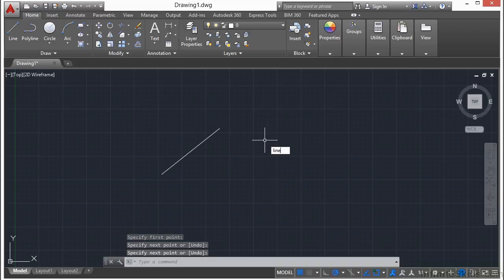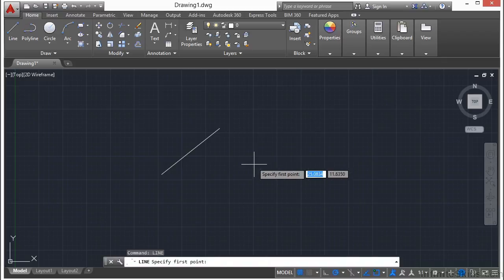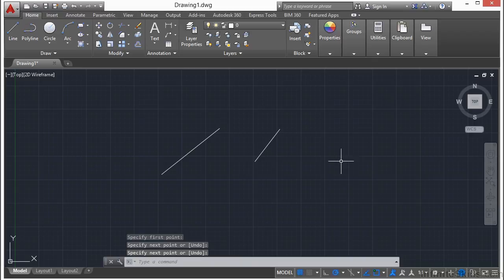Also, I can just start typing. I don't necessarily have to put it down in here. What's going to happen is one of two things. Right now I have on what's called dynamic input. That means I'm inputting dynamically while I'm working right at my cursor. This sort of emulates a smaller, more condensed version of the command line. And you see I can start drawing lines right away.